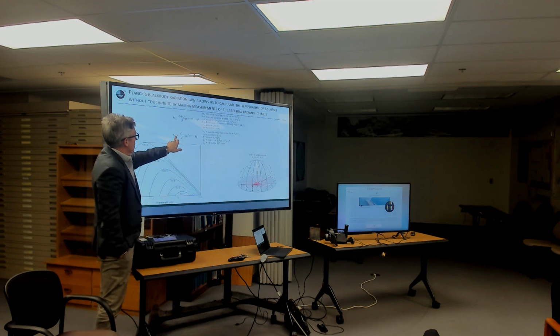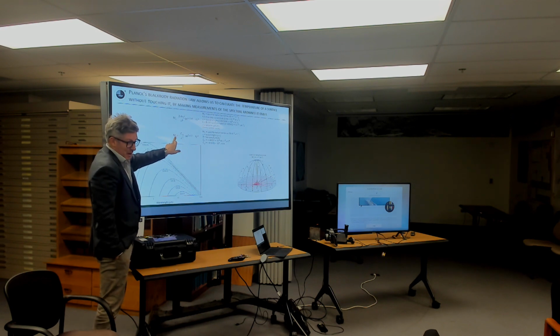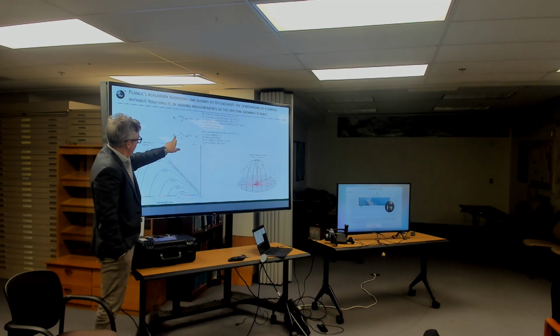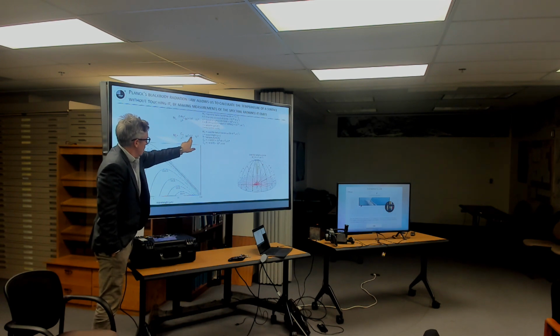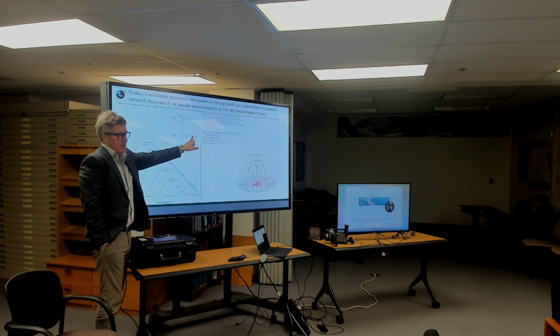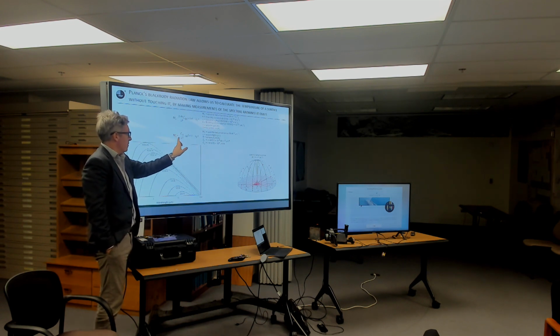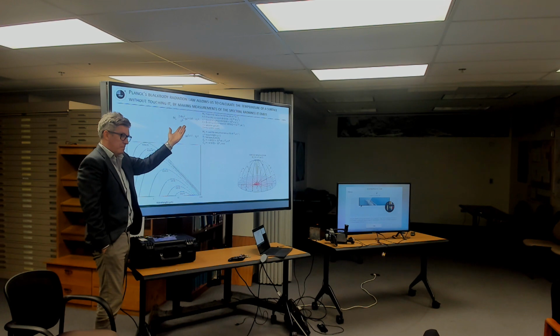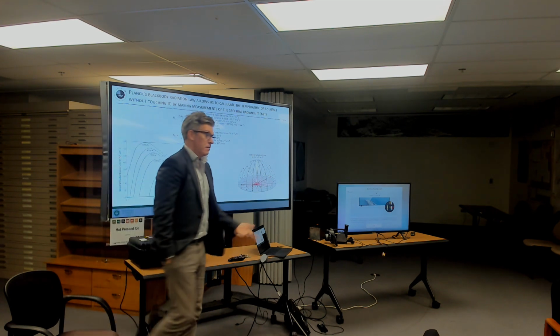Again, this is the thing that we measure, or this is related to it, right? Remember, we have to divide this by pi to get to spectral radiance. But that is related to a whole bunch of constants, and wavelength, which we can just iterate through, and the only unknown is temperature. So if we have a measurement of this, and we know the wavelength at which we made that measurement, we can easily invert this to work out the temperature of the surface. So it's pretty easy.